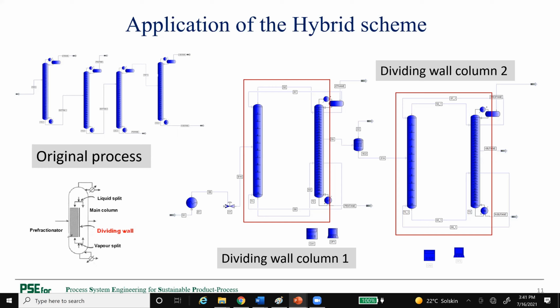And so in the second column, there are more stages than the first column to account for the stages above the dividing wall section and below the dividing wall section. So this can be configured, and it's not that easy to simulate them because the flow rates between the columns are very sensitive. But one can find the solution. And so an important question with these columns is the operability and control. That needs to be looked at in more detail. And people are doing that.